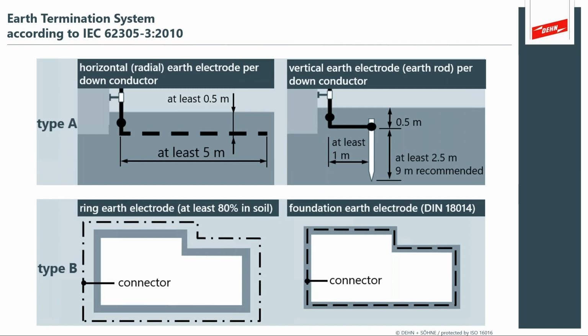Foundation electrodes are very interesting too, because it's an effective way to do it. The encasement can help preserve the integrity of the actual buried copper wire, and that can be very effective too.